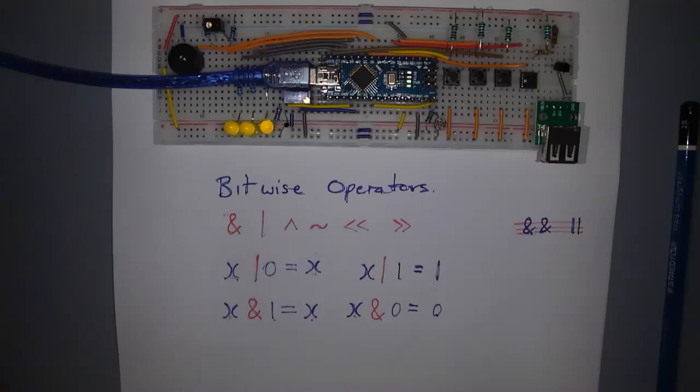But there's an in-between process, sort of semi-readable code called assembly language. And this assembly language is then converted into this machine code. And this command in means take the value 5 and read, well actually, no. Take the address number 5 in our microcontroller, which in our microcontroller corresponds to port B, and drop it into a temporary register R25.